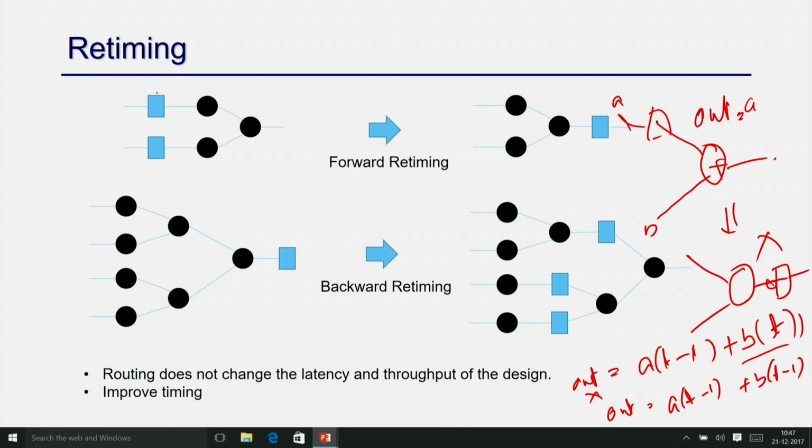You can only move it to the output if there are resistors in both the inputs. Similarly, if there is a resistor at the output, it has to be moved into both the inputs, right. So you cannot just move into one of the resistors. So it will come here and here, you remove this, and then you can again move this to here, right. So you can move this. So that is what I have shown. So that is moved here, and this again moves to both the inputs.